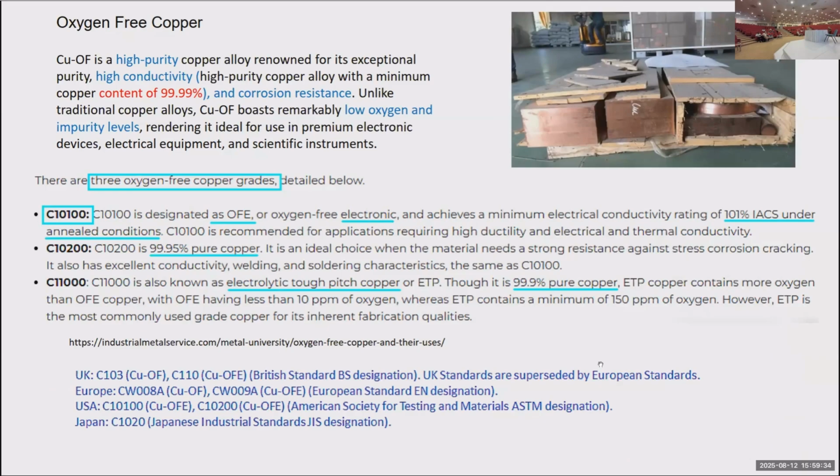Oxygen-free copper is the most conductive copper. Because we have shown that the quality factor depends on the surface resistance, it means the real part of the complex resistance. This is around 1.1% more conductive with respect to others.